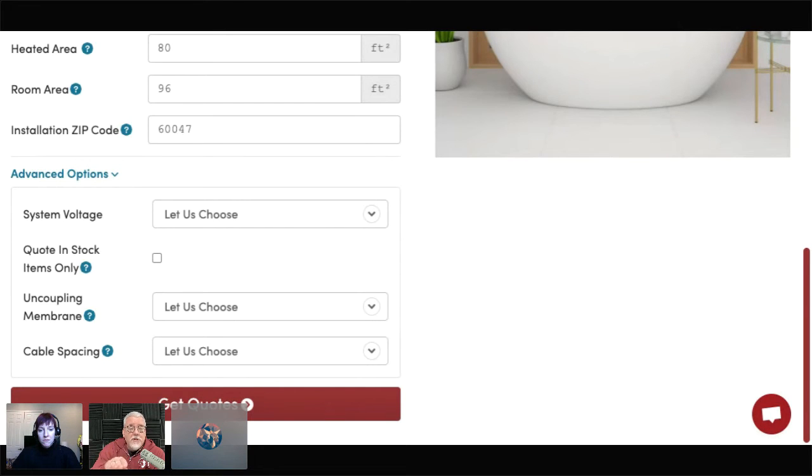Well, would you rather start with a floor that starts at 70, that can go up to 79, or would you rather have a floor like tile, which you could actually heat into the hundreds without any problem? So which one is going to deliver more heat into that 3-season room? Tile will, because it can go way past 85 degrees and it can add more heat into that space. But these floors that have limited temperatures like LVT, laminate, and carpet, those will not deliver as much heat into that space. So we get that question all the time.